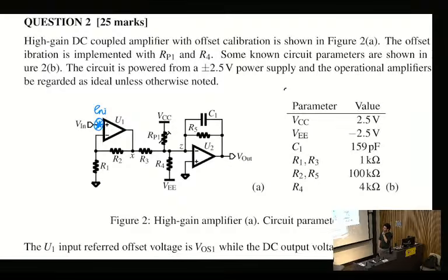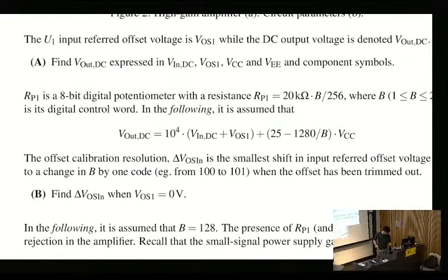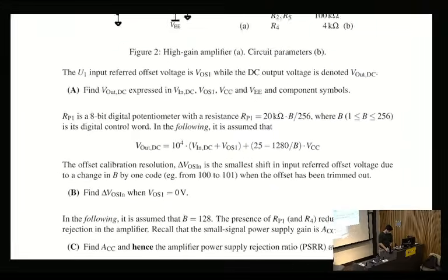Yeah, so the problem is we have a connection. So even if we just look at this formula that's down here, we have an output that is dependent on VCC, right? So that means any ripples in the power supply are going to be amplified by that gain there. So even though it's not the power supply rejection ratio problems we're used to, it's just some sort of connection from the power supply to the output that has a gain that will decrease our ability to reject ripples from the power supply. Okay. What are some ways we might be able to fix this?